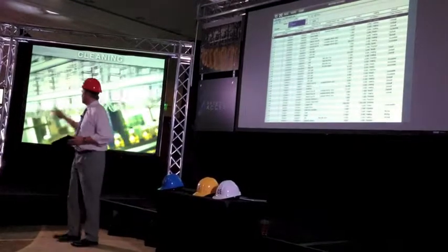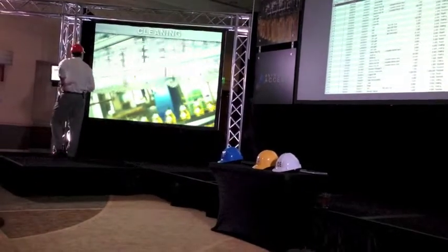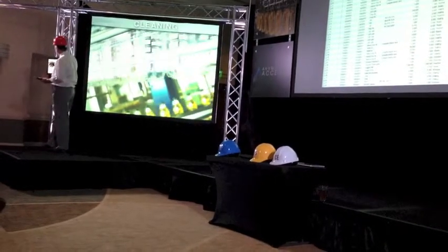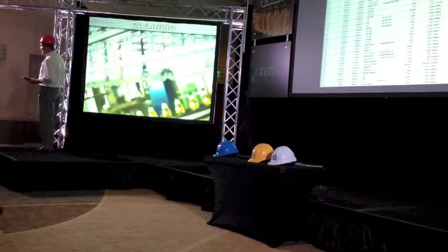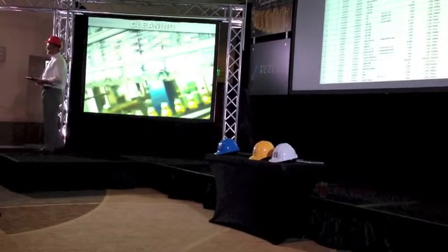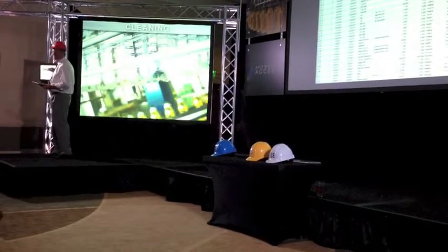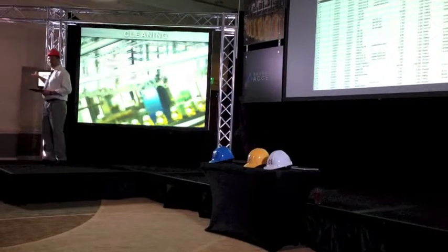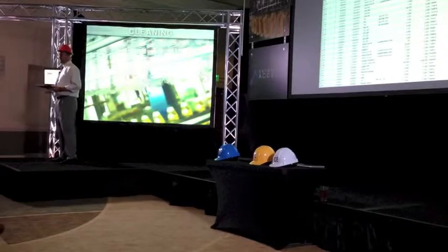Okay? So I'm going to go over to the cleaning area, and I'm going to look at the process, and I'm going to say, you know what? I've seen this before. You've got jets that come down in here, and they put a mixture of water and Cascade, cleaning detergent, into the bottles, and then they come over here, and the bottles are dumped, right? So probably what's happening is one of these jets is not working properly. Maybe there's a broken valve.